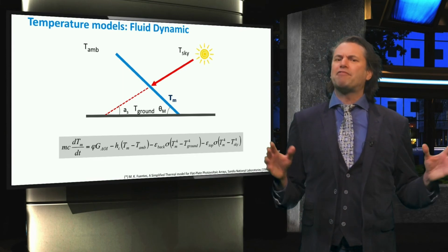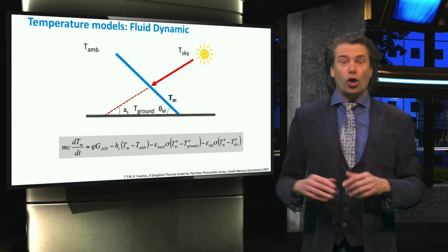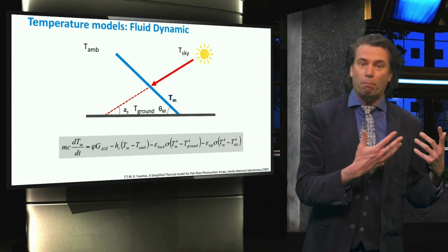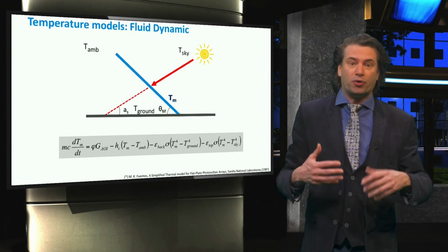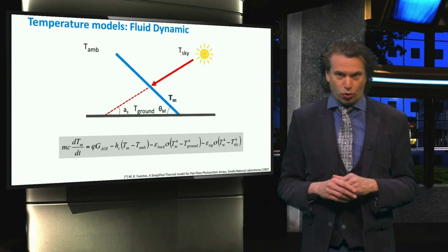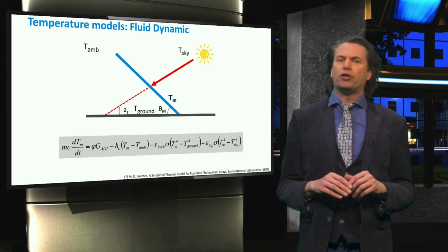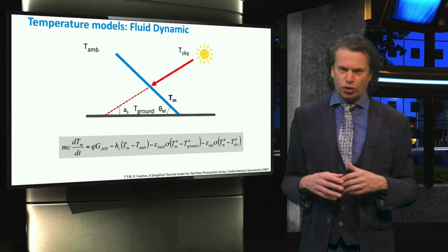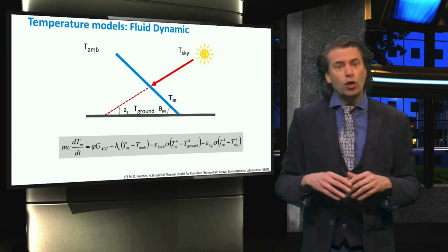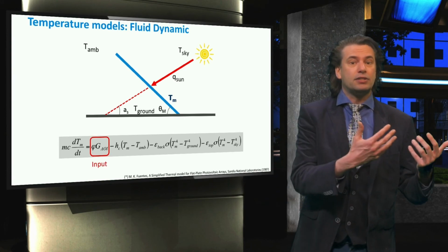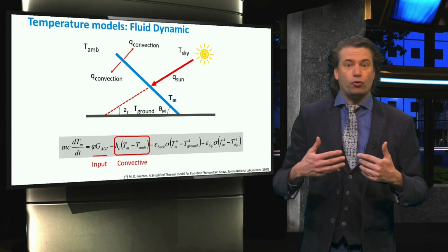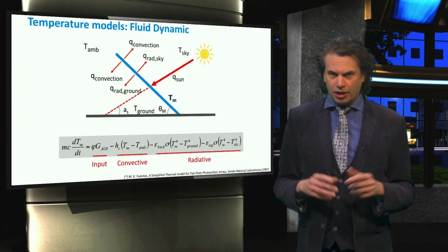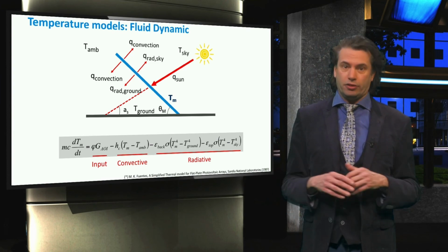In week 4, we have discussed the effects of temperature on the external parameters of a solar module, and we also presented different models to calculate the operative temperature of a solar panel. Most of these models are empirical, but we also looked into models based on the thermal balance of a PV module, which takes into account the incident irradiance on the module, the convective heat transfer, and the radiated heat transfer. This model can be solved using an iterative process.